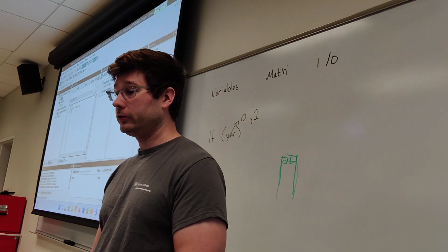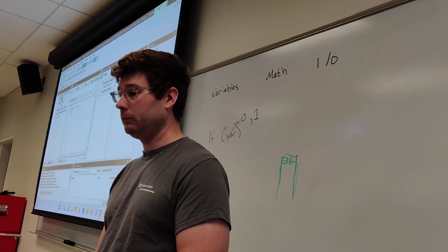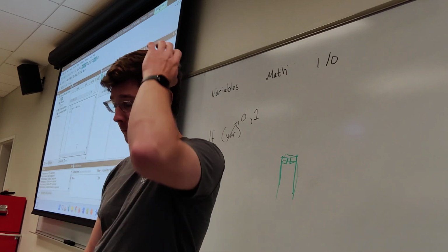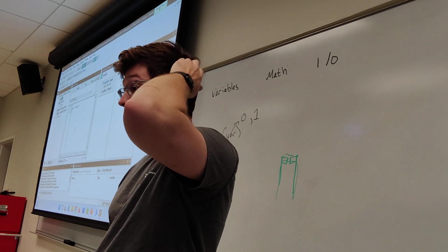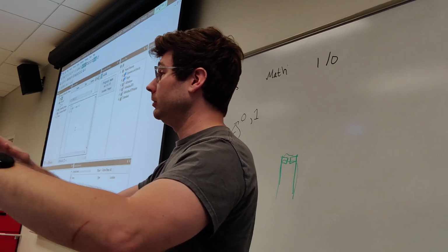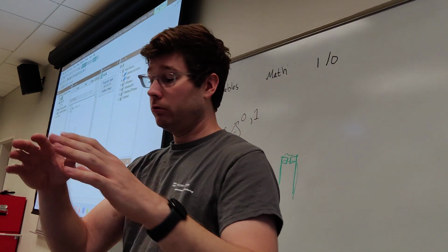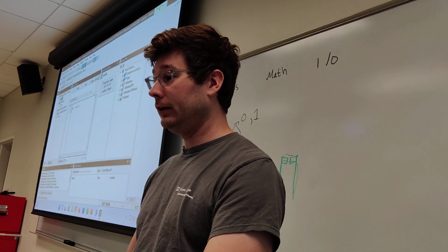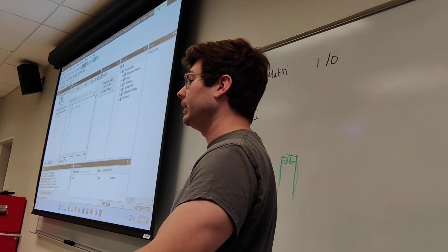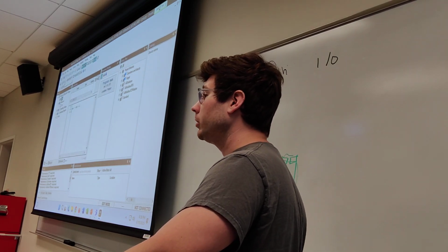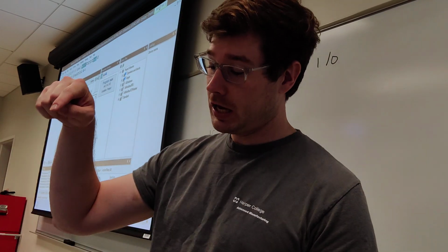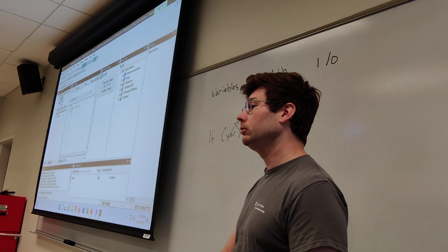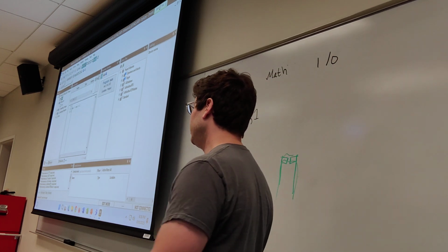Assuming you compiled this already, I'm not going to compile it because it would recompile and take a while. What I want you to do next is upload the code that is compiled and living on our PC to the device. We do that with this button right here. See how it says download PLC code? It pushes the compiled code from our PC and burns it onto the PLC. We can do that over and over again.